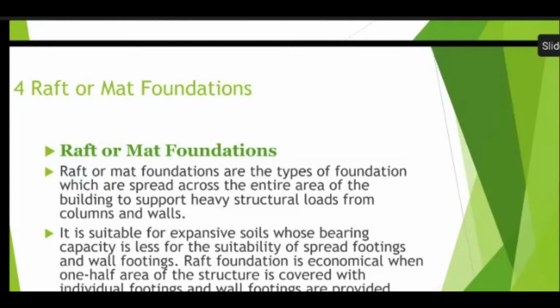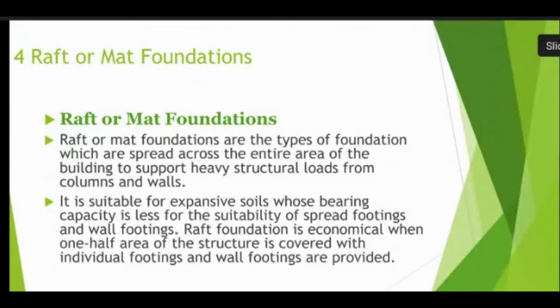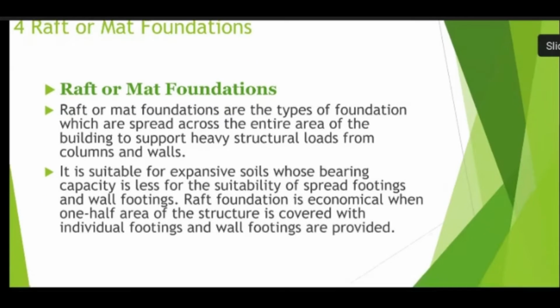Fourth, raft or mat footing. Raft or mat footings are the types of footing which are spread across the entire area of the building to support heavy structural loads from columns and walls. It is suitable for expansive soils whose bearing capacity is less for the stability of spread footings and wall footings.